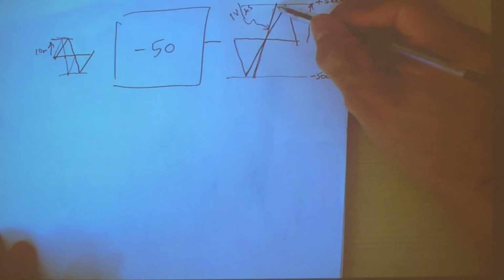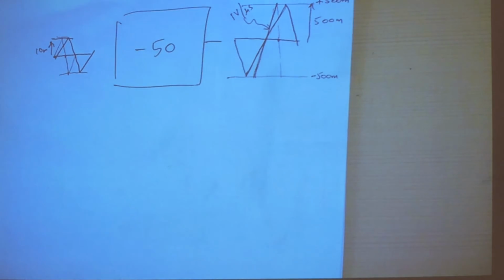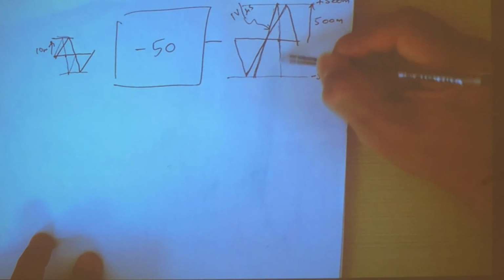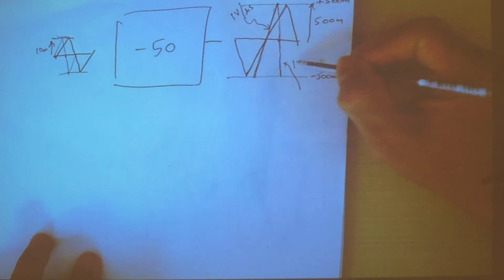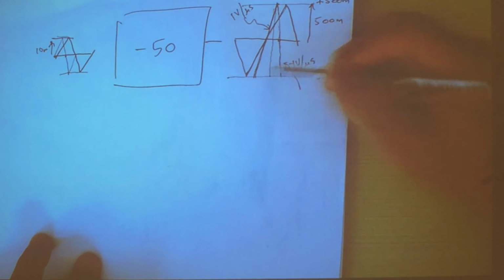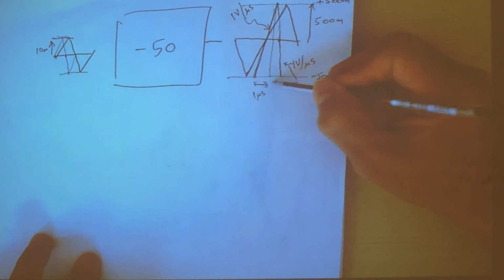But when that happens, of course, the frequency is very much higher. And of course, the zero crossing points become closer to one another because the frequency would have increased. So now this slope will be 1 volt per microsecond. So as it comes down, it is also coming down at minus 1 volt per microsecond. Right? So I take the center point, I divide this into 2. This will be 1 microsecond. And this side will also be 1 microsecond.